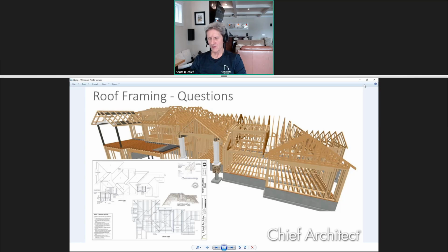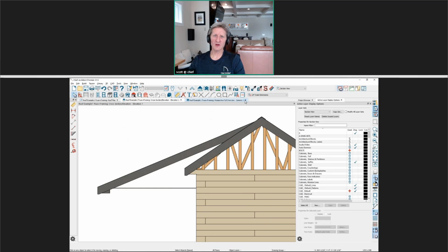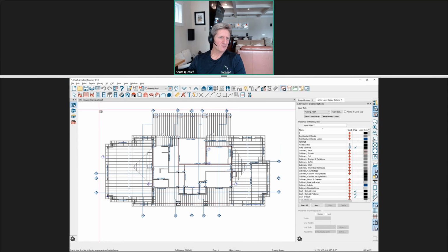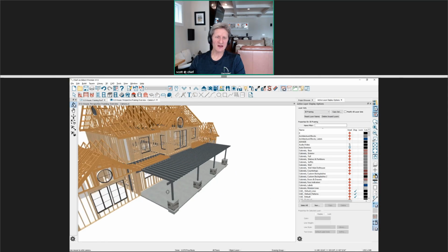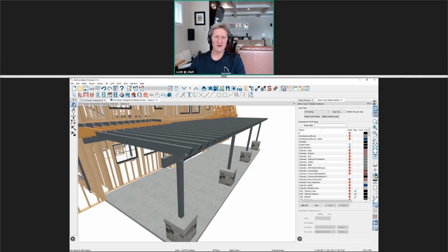Well, John, I'm not sure that we've made a significant change in the way rafter tails work with respect to roofs. One of the things that we have done is we've enabled it to work on non-rafter members. Take our overview here. You can change rafter tails or exposed tails on other items. So if you zoom in here and look at the trellis, that's just a general framing member.